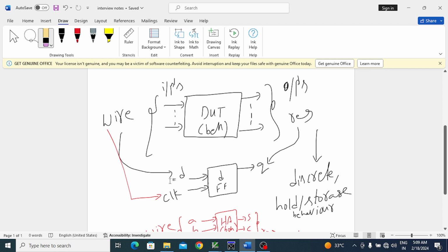Now I am giving my input, and based on this input at this clock edge I may get an output. Until getting that output, it has to store the present output. To store that present output, it should be a reg. That's why output should be a reg in behavioral style.